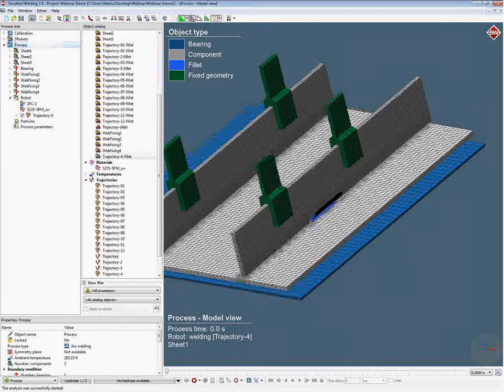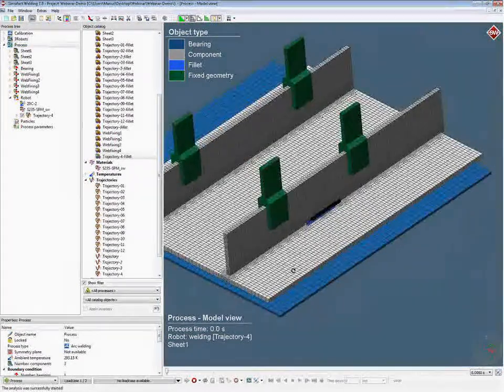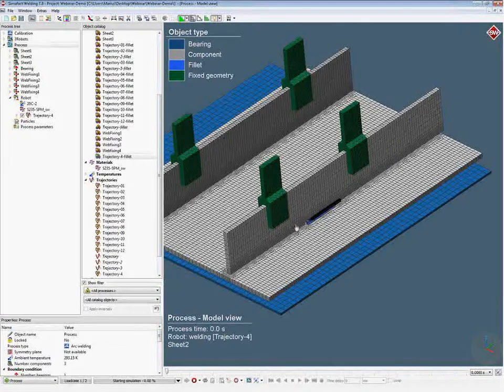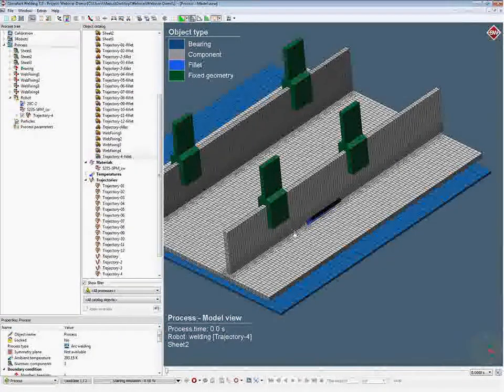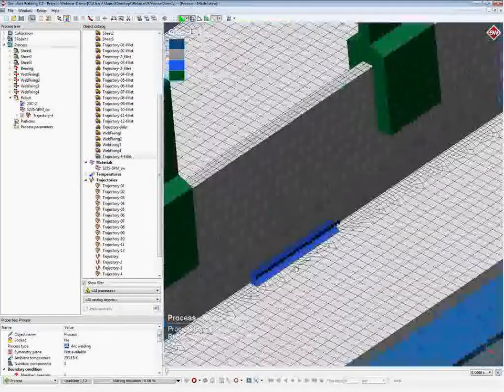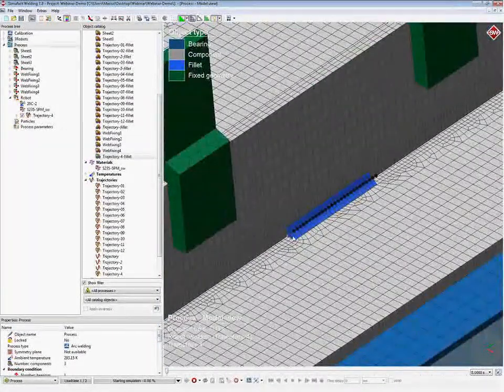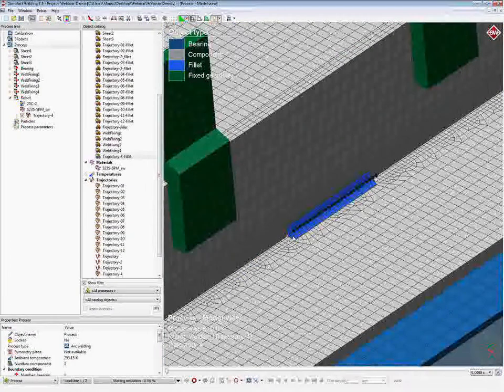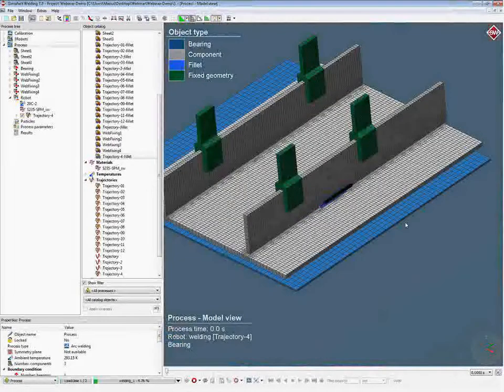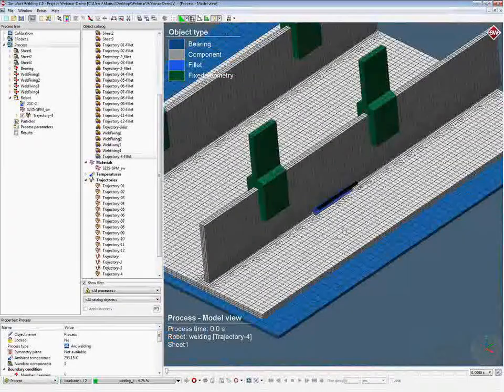The thing that you need to understand is that welding simulations usually take a considerable amount of time. This is due to the sheer fact that we are dealing with phenomena that are very localized, usually on very large structures. So in order to have a good mesh, you need the kind of mesh that you see here, which is typically very fine in the diffusion zone and a little bit more coarse in the outer regions.